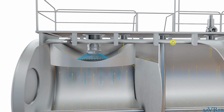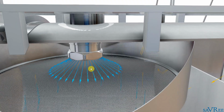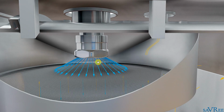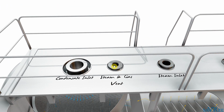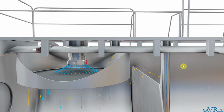It will enter the top of the deaerator, and some of the steam will also rise up through this section here. Looks a little bit like a demister. And as it rises up, we've got a very large contact surface area between our condensate, which is being sprayed in, and our steam. And as we heat up that condensate, it's going to release a lot of the non-condensable gases, and we're going to vent those non-condensable gases and a little bit of steam through this pipe here, which is a vent.